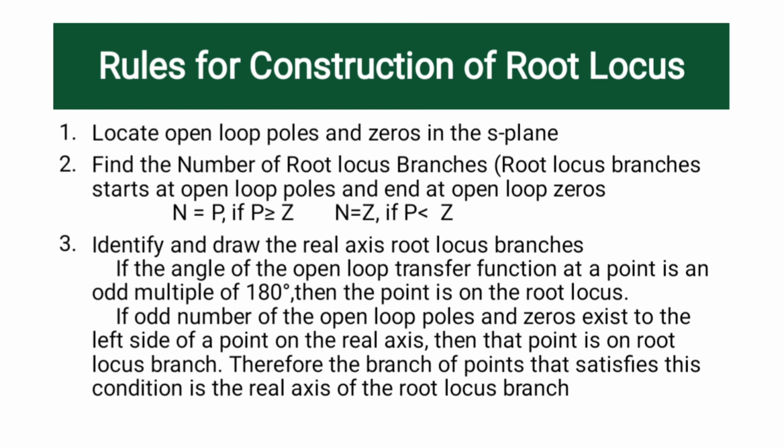Then the root locus diagram is plotted against the roots of the characteristic equation and the controller gain value. Write the characteristic equation in polynomial form, substitute a value for k, assume different values for k, and find out R1, R2 and R3.